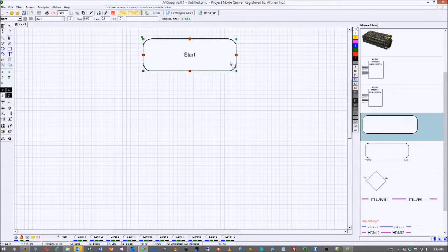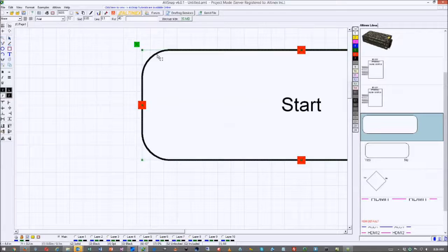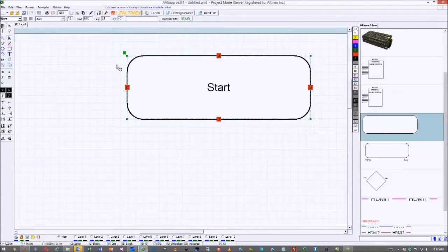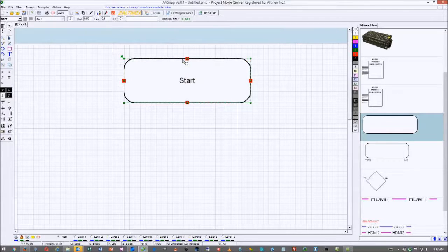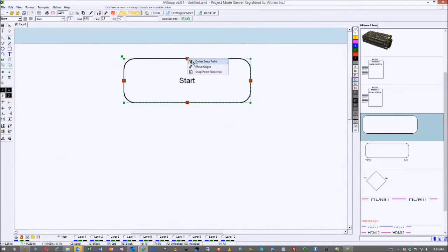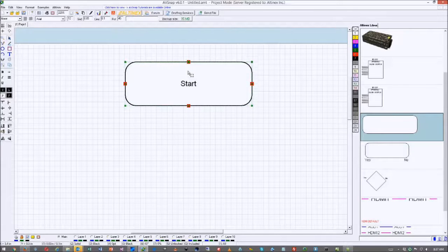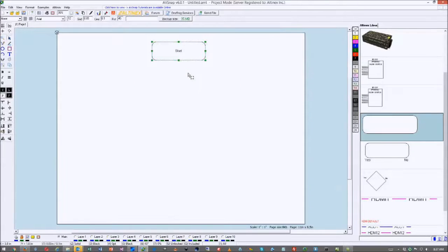Okay. If you don't want it to be adjustable, then just don't do this. Now notice that my origin is a little bit off, and because it's a little bit off, I cannot really set the origin. So I'm going to come back here and say, move the origin to here. Right-click and move origin, and now it will lock in really nicely on the center of it. So you can fine-tune things that you need to fine-tune.